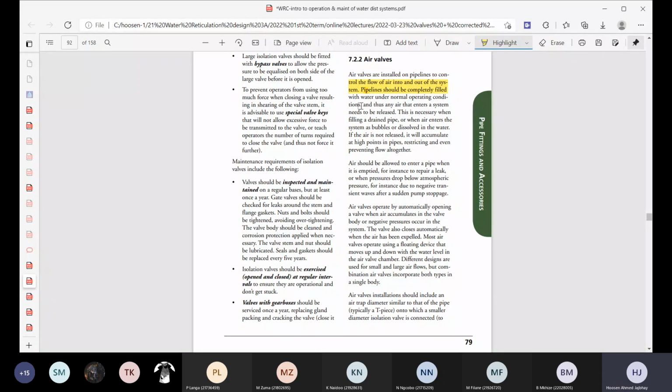Under normal operating conditions, if you have air in a pipeline, it can throttle the flow. You may get air trapped at a high point in the pipeline, and then you get what we call an airlock, and the cross-sectional area of the flow is decreased because of the presence of air in it. I made this just to explain that further to you. I'm going to try and visualize it. If you have a pipeline shaped like that, exaggerating it like that, and air rises, then unless you have a very high flow velocity, the air will get trapped over here.